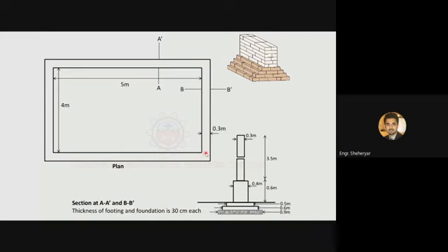Similarly, if you take from this point to this point, again you are repeating this portion in this wall, because this is also already considered in this vertical wall. So in this case, it will be a little difficult to estimate the quantities because we have to avoid the repetition of the areas or volume.